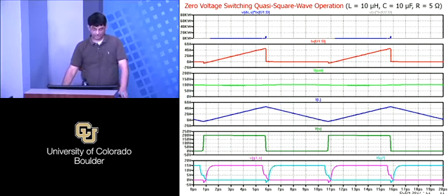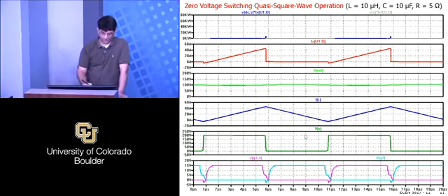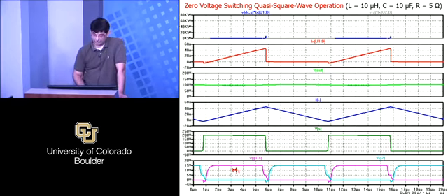All right, here is the simulation. Again, you have first M1 on here, and then you have M2 on. The switch node voltage looks just the same as before. Here's the difference that we expected, that the inductor current has higher ripple, right? The average value is still 20 amps, but the ripple is considerably higher. In fact, probably 10 times higher, because we have a 10 times smaller inductor. The output voltage has slightly more ripple, but not appreciable. It's still fairly flat.